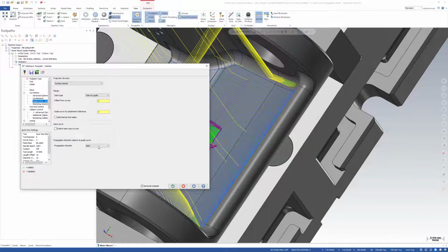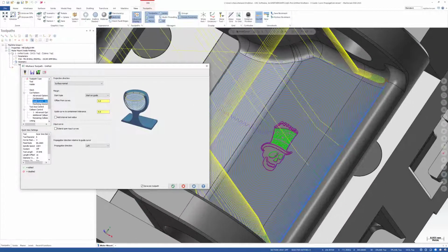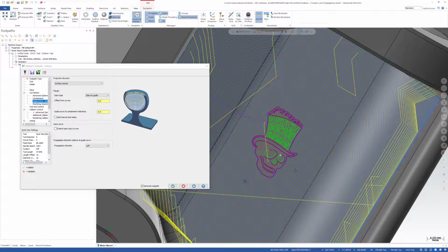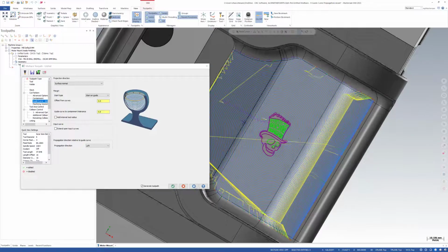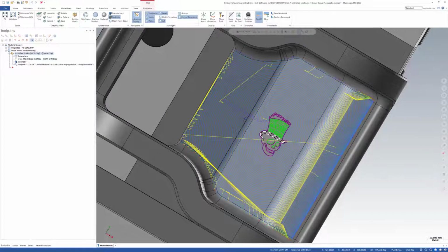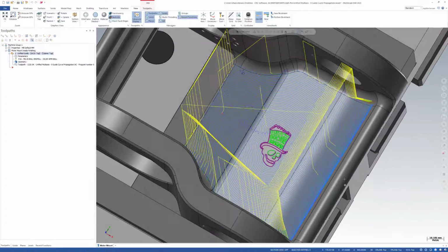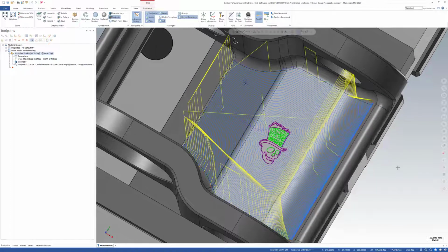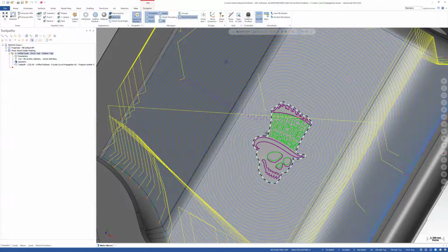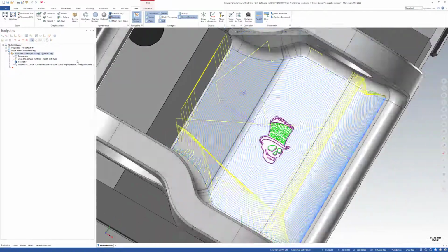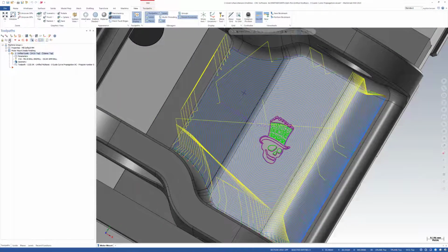There's this option here called Propagation Direction, where I can say only propagate to the left. And now we get this really cool effect that only runs from the outside of the surface to our guide curve. So essentially, picture what it would take to get this style motion without using this option. We're basically trimming out maybe a collision control area or something like that. But that would be even really hard because the passes are essentially being generated by our collision control area. So this is a really cool way to create some motion.